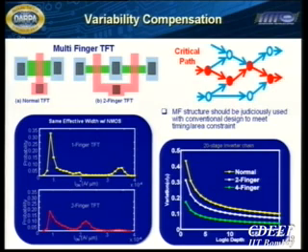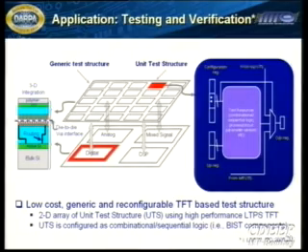So the one that really comes to my rescue is basically what you do in analog design. And in fact, these days, even in digital design, you use multi-fingers, right? Rather than having one finger, you actually have multi-fingers. If you have a normal TFT versus a two-finger TFT, one can do a statistical analysis of it, and one can show that, from the variation point of view, the multi-finger is way better than a single finger. Right? That's the one that we looked at, along with the fact that in this particular case, I might actually have to do reasonably worst case design.